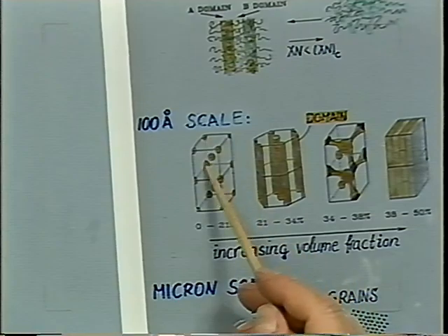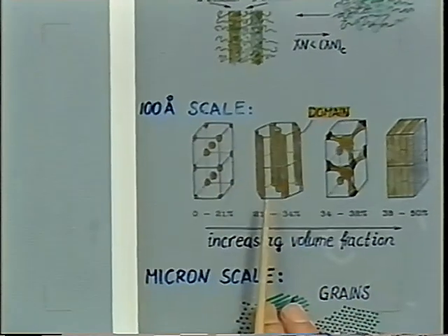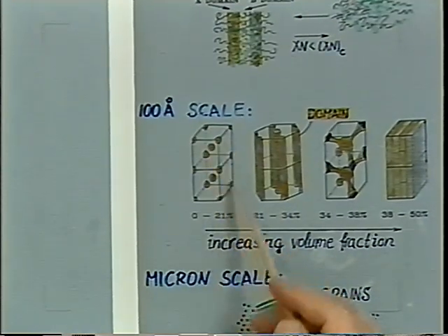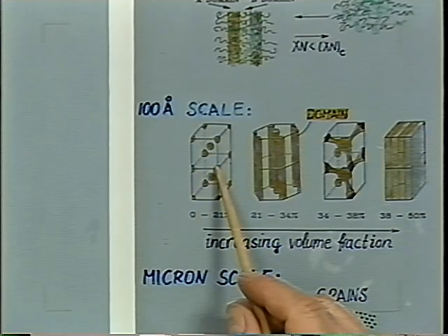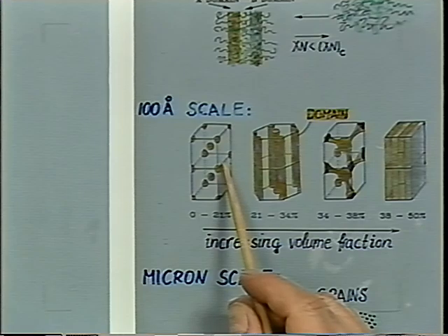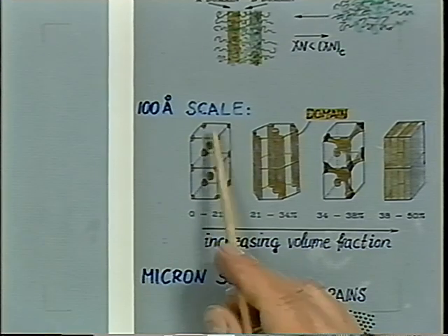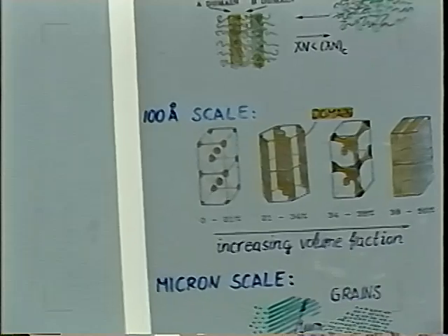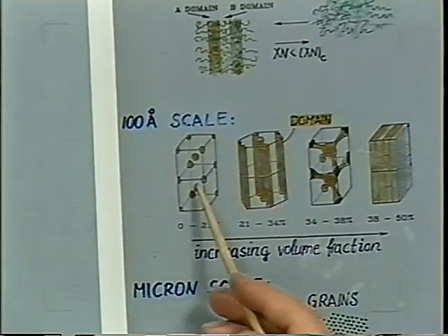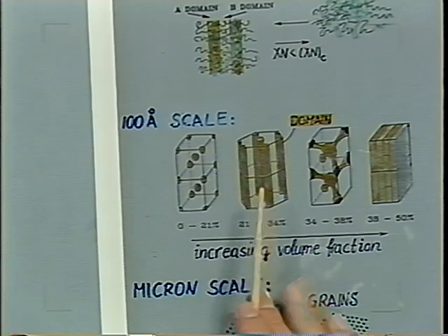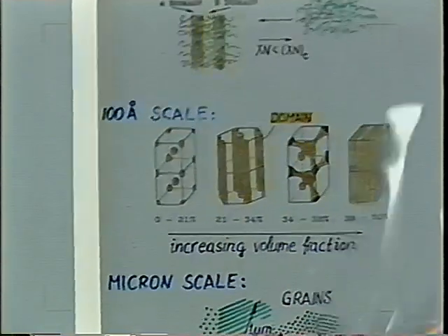regularity here, if you have just a small amount of one component on a regular lattice, that small amount hinders the motion of the molecules, and it has a large effect. It's not like a filler. It's really an ordered system, and rheology is drastically affected. In some ways it looks similar to the rheology of the structure with cylinders. It's not as extreme.